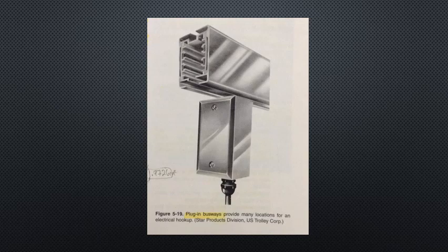This is a very important point, so let's repeat it. Overcurrent protection of busways is required at the supply end. If a smaller busway is tapped from a larger busway, overcurrent protection at the tap point should protect the smaller busway. An exception allows a short tap, 50 feet or less, with an ampere rating of at least 1/3 that of the overcurrent device protecting the larger busway, to be exempt from the required overcurrent protection at the tap point.